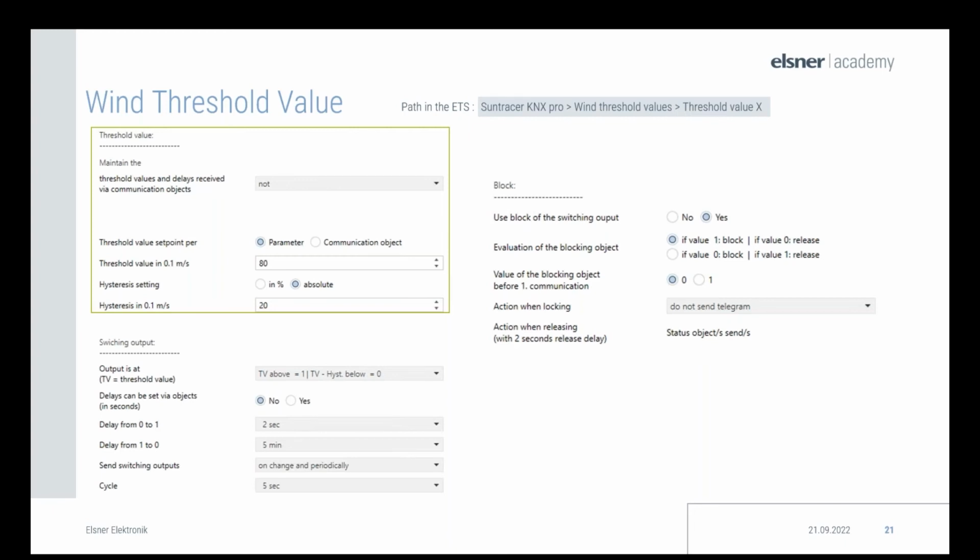This is a very important functionality because, for example, if you have a wind alarm and the wind is very strong and you know, for example, that your blind manufacturer said our blinds can only withstand 4 meters per second, it's very important that the blinds retract if there are some very strong winds. But after a couple minutes, if those strong winds are not there anymore, then you want the automatic functionality to start again. So this is basically a saving mechanism, so no damage is caused due to too much wind. More about this later and more in the next graphic.